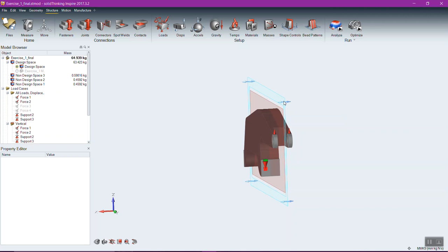So design for manufacturability is critical when you're using software that is helping you understand the shape of your part. And that's what this little blue rectangle is doing. If we come up here to our shape controls, we have single draw, split draw, and extrusion. Single draw is that punch and die that I was talking about, or just a simple pour of liquid into a mold. Split draw is when you're coming at it from both sides. It allows a little more flexibility because you've got two molds that come together to form a cavity and then can split apart. And then extrusion.